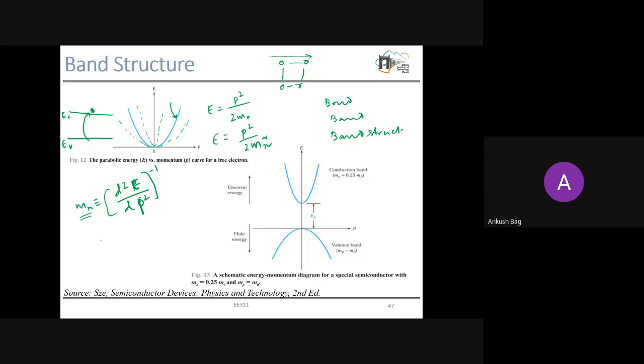That means you know this in current and everywhere. So when we need to calculate, or we need to consider the mass of electron, then we'll consider this effective mass. Now if this effective mass is high, that means you have a heavier carrier, so it will not move easily. So the mobility and all other things will not be very good, like if you have a heavier carrier, it will not move easily.